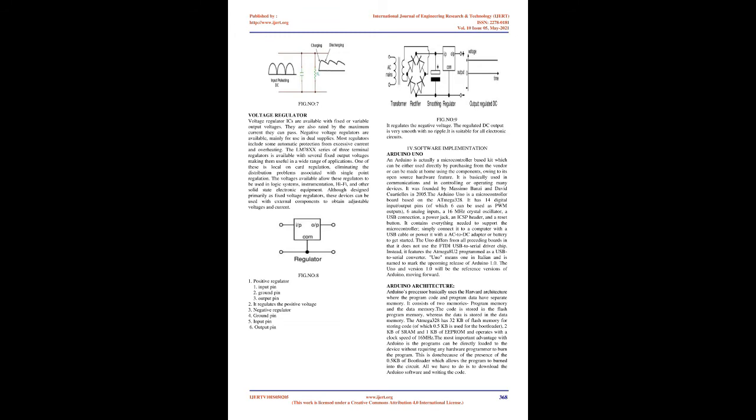The action of the reservoir capacitor on a half-wave rectified sine wave. During each cycle, the rectifier anode AC voltage increases towards VPK. At some point close to VPK the anode voltage exceeds the cathode voltage, the rectifier conducts and a pulse of current flows, charging the reservoir capacitor to the value of VPK. Once the input wave passes VPK the rectifier anode falls below the capacitor voltage, the rectifier becomes reverse biased and conduction stops. The load circuit is now supplied by the reservoir capacitor alone.